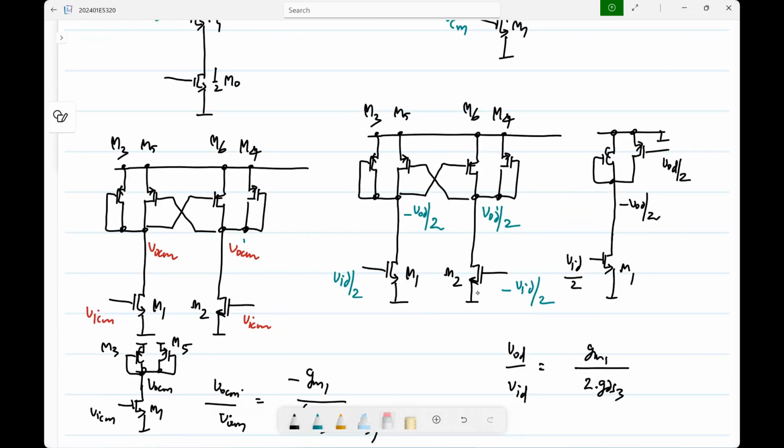Now, in general, how do you make amplifiers? You make currents flow through impedances. To have high gains, you should have currents flowing through very high impedances. Now, this should happen for the differential picture. For common mode, ideally, you don't want the common mode to vary at all. That means common mode impedances should be 0, a short circuit. Of course, you will not get 0, you will get some low value.